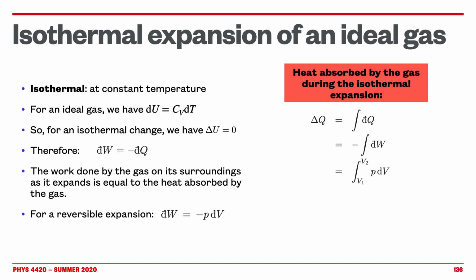Why can we calculate this? Remember, pressure is not a constant. It's not at all. However, we know that it's an ideal gas, so P is actually equal to RT divided by V. It's the ideal gas law. So I can substitute and I can get this equation right there. And now it's nice, because R is the gas constant, so we can take it out of the integral. T, we can also take it out of the integral, right?